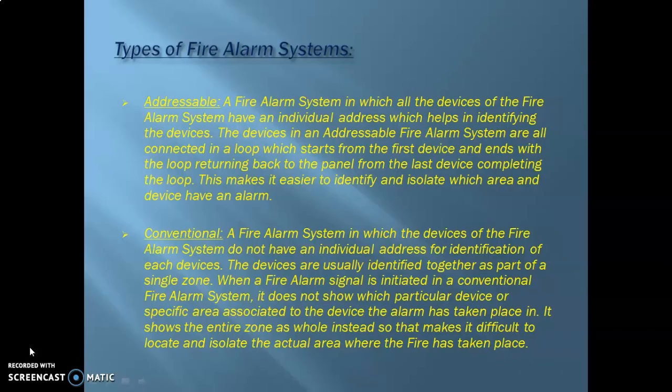Instead, the panel simply shows the entire zone or the area where all the devices are connected together, and so this does not make it as flexible and desirable as the addressable fire alarm system. Of course, this type of fire alarm system is especially useful in protecting small buildings or shops or any area that does not require a large number of fire detection devices.